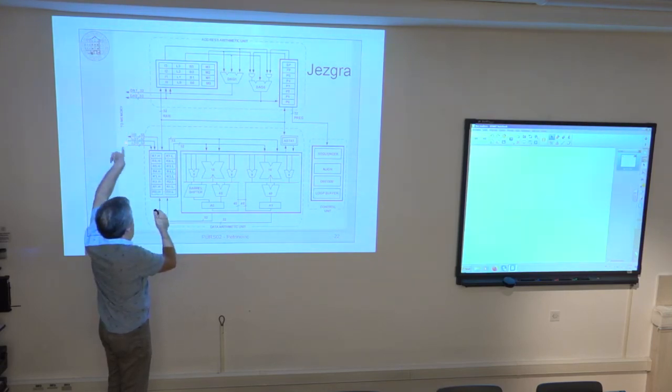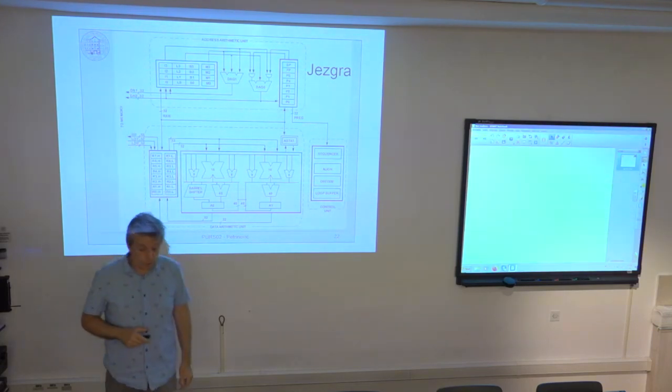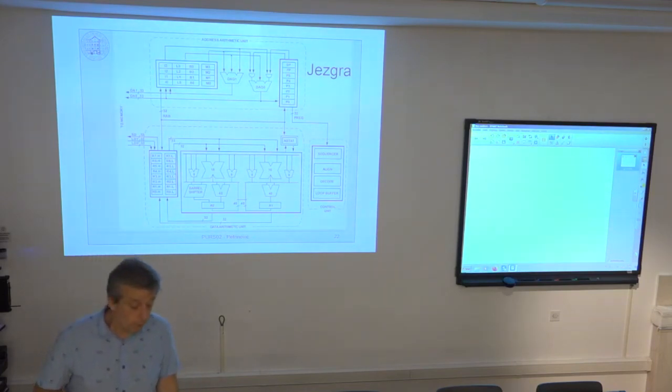So to memory and back from memory, the content from these 2 addresses is returned to the core. And in the core, it can be only written into a register file. It cannot be used directly in execution units. It must be first written into some of the registers and then used from these registers as an argument of ALU or back instruction and so on.